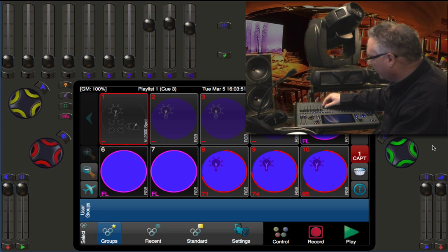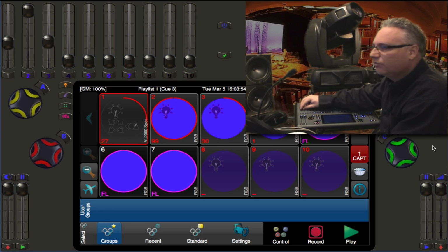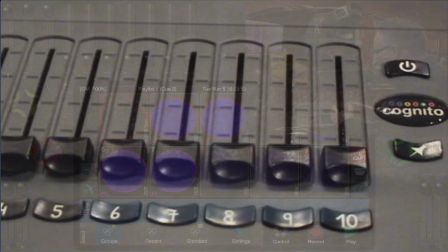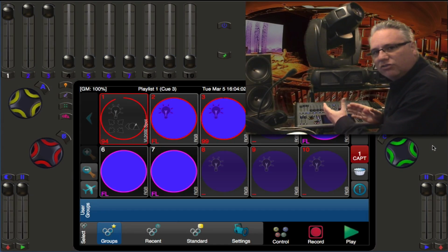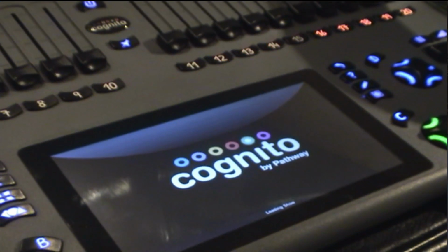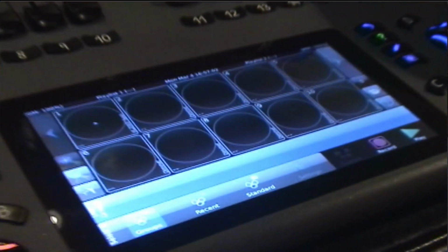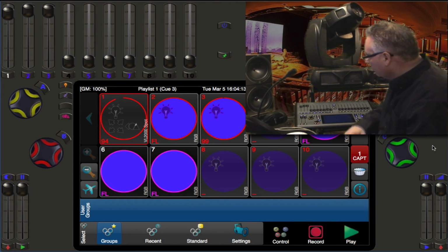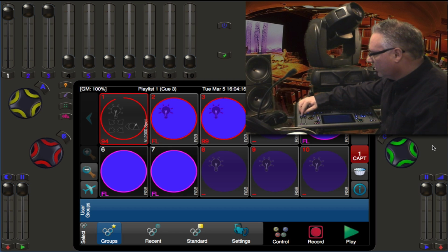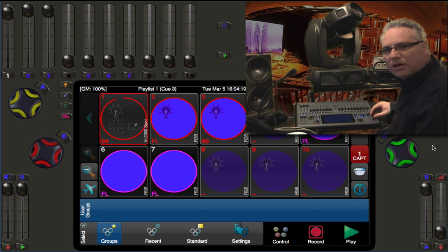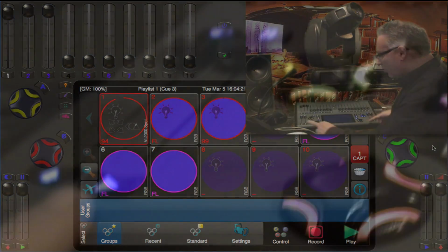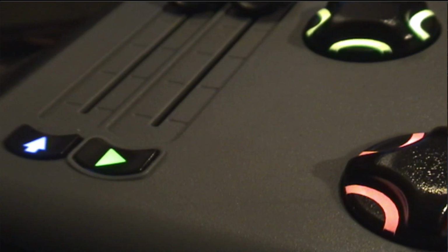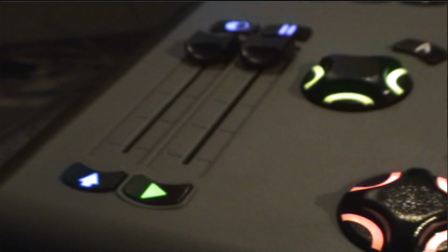Looking at some of the hardware elements here, it has faders, which you can obviously use to run the intensities of your lights. You can also record memories to these. Front and center, most importantly, is the 7-inch capacitive touchscreen, which is where you will do most of the interaction with your lights, their effects, where you record them onto playlists, how you label things. There's a Grand Master and a blackout button, a Memory Master with its blackout here. There are two playbacks where you can load on playlists and play multiple, 2 or more, at the same time.